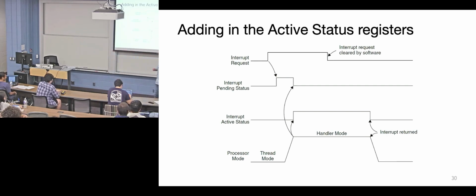For the interrupt request, what decides whether or not the interrupt request gets cleared by the software? It depends how that interrupt has to be handled. Usually it's some register you have to go in there and reset. So you may be in your handler, and part of your job is to reset that interrupt request. Could be, yes. It depends, you can also have hardware that clears itself. It basically gives a pulse instead of holding it high. So that's peripheral dependent.